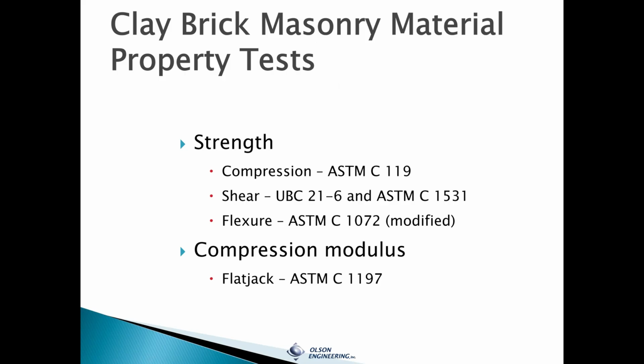Yeah, at the last minute this morning, I decided to put in some testing to give you a little perspective on some semi-destructive testing options. I'm going to go through this very quickly so we try to finish close to 10 o'clock. Obviously, prism testing can be done. That should have said ASTM C1196; I got a typo there. Also shear testing, flexure testing, and compression modulus with a flat jack. And the strength can also be done with C1197.